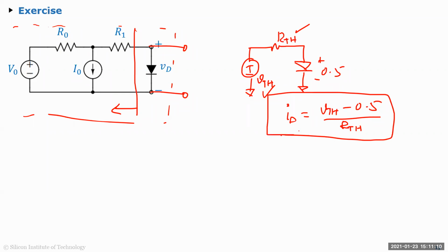So sometimes when you have nonlinear elements, you can do tricks like this. Or if you know that the nonlinear element is actually linear for the very small range of voltages you're calculating, you can do linearization. That's what we're going to talk about in the first analog class next week, and it's the only thing missing from your device physics part: the small signal model, which in digital you'll never use, so we never covered it.